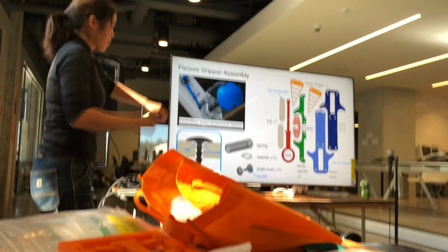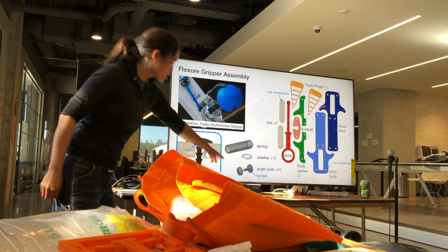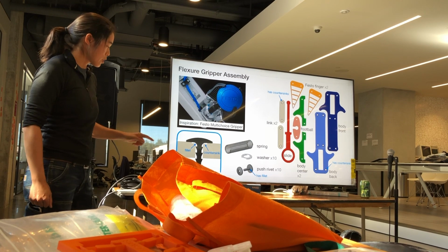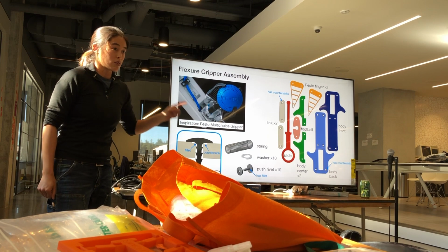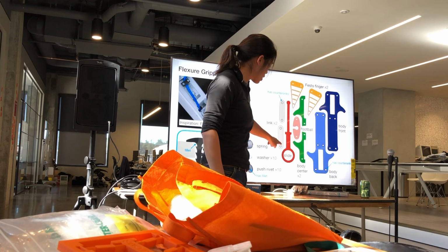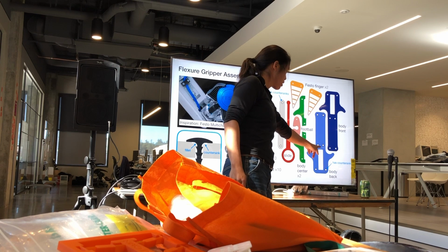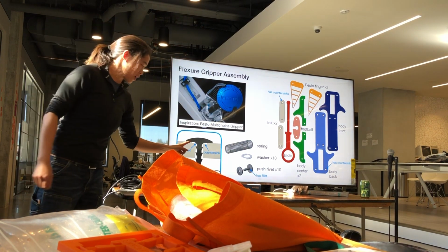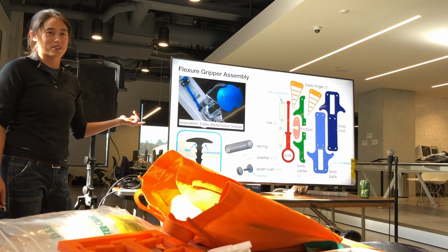Okay, talk about this. The main thing I want to go over here is that I'm using these push rivets to put everything together, so no tools are required. The rivets have a fillet on the underside of the head. Certain parts, namely these two link shapes and only one of these body shapes, have laser etched counterbores. The purpose of those is to provide clearance for these fillets. I'm pretty sure the things will still work if you put them in backwards, but they'll work much nicer if you have them in the right way.